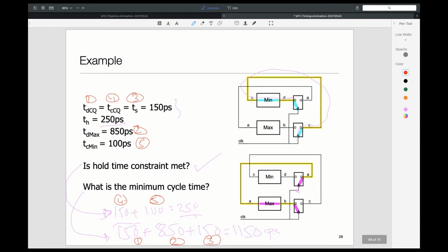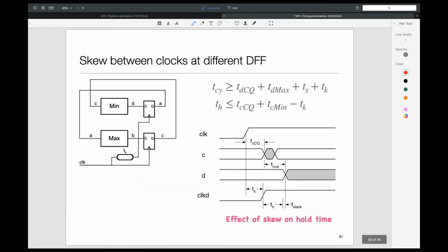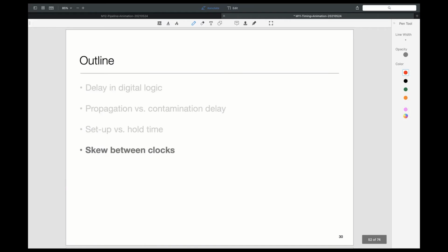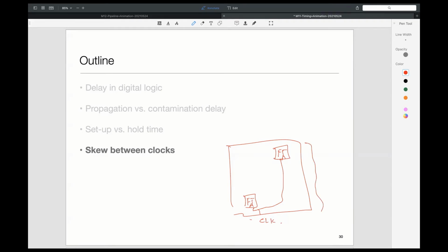Wires have capacitance. Imagine a chip where the clock enters the chip at one part, right? So this is what I'm trying to say. Let's say there is a flip-flop here, and let's say there is a flip-flop here, and let's say my wire looks like this. Now, how long can this chip be? Well, nowadays, big chips could be around a couple of centimeters, let's say 3 centimeters worst case. And this is within the chip. Same story holds true at the level of the whole board.